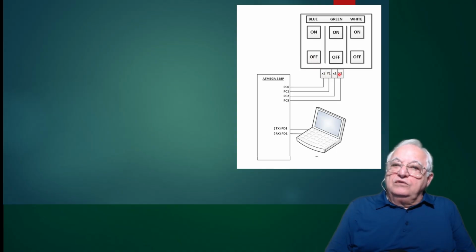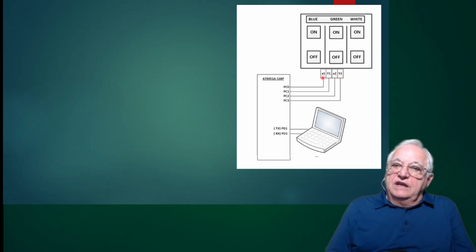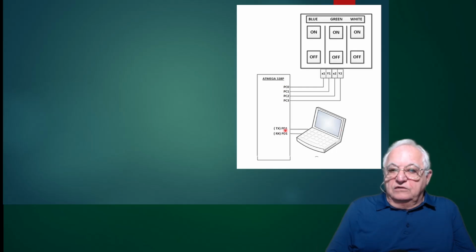And then we are going to connect to the microcontroller X1, Y1, X2, and Y2, so we can provide the voltage and read the analog feedback. And then we're also going to provide a means to send the information to the laptop.